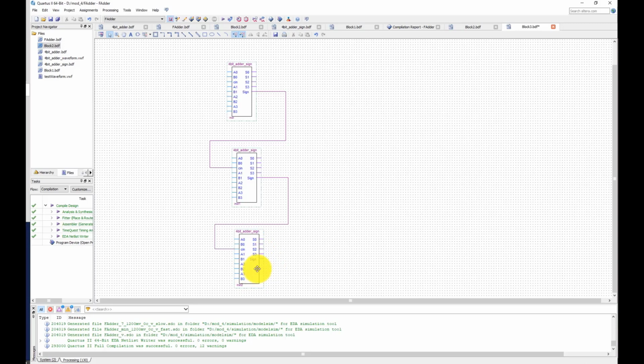In order for this adder to work, we need to wait until the last carry out from the full adder number 1 here to be computed and sent to what? To this full adder. And remember, we are doing this operation on a huge scale. What we will get is a huge delay and a huge latency.